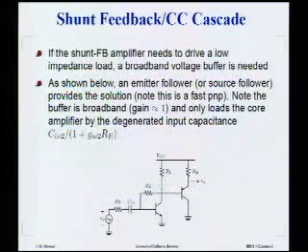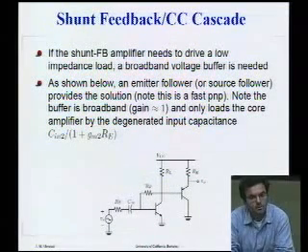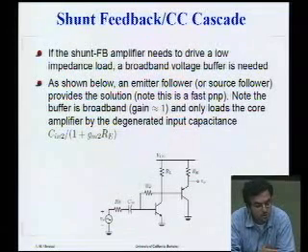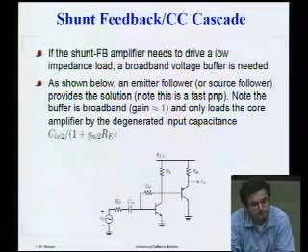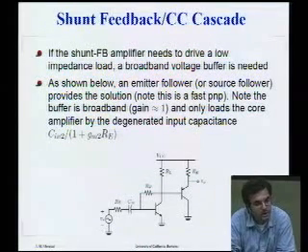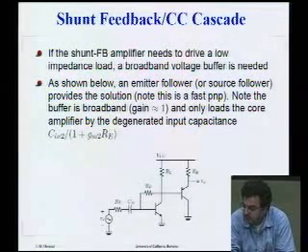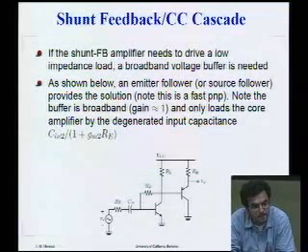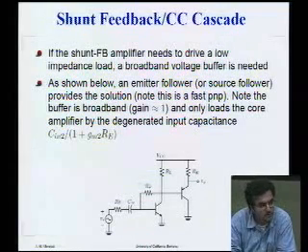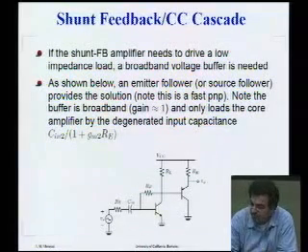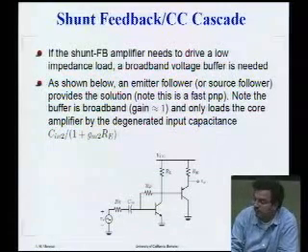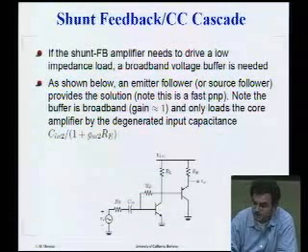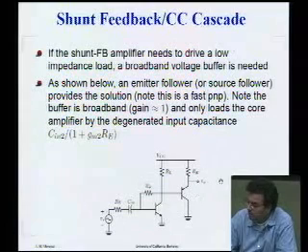One last thing I should mention is there are situations where this amplifier will interface where you need an amplifier that needs to interface from a low impedance up to a relatively high impedance, right? And because this is shunt feedback, both the input impedance and output impedance are relatively low. So if you need to interface it with another impedance level, whether it be higher or lower, you need to buffer it. So here I've shown an example of where you need to buffer this, let's say, to a voltage signal.